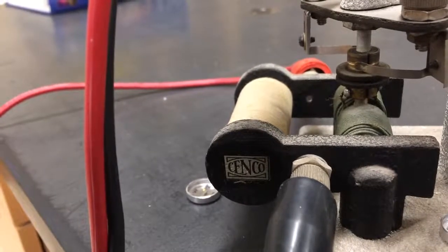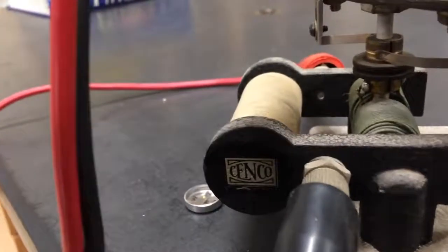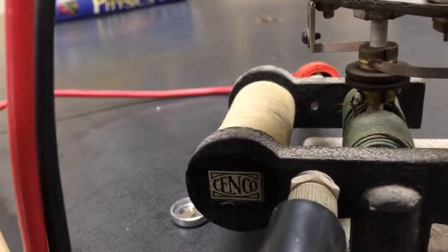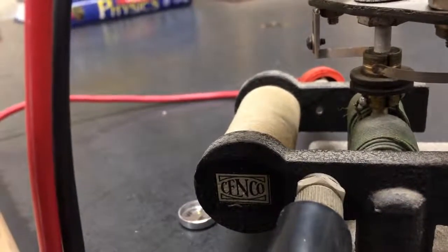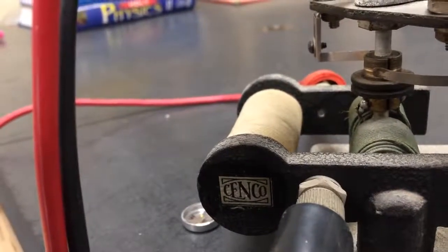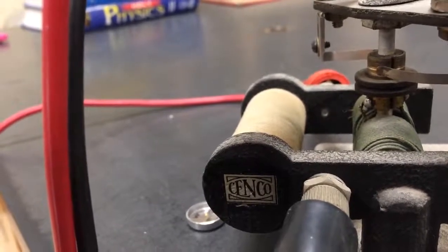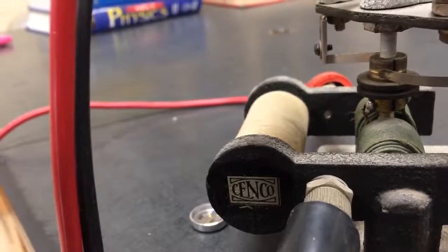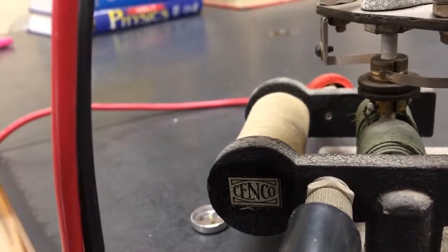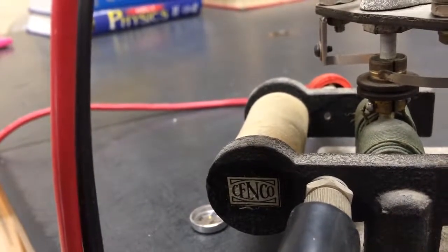And they alternately touch one side of this metal spinning jacket or the other. And what that means is it's constantly switching back and forth, whether positive or negative is touching each side of the jacket, and that means the coil is reversing the direction of its current, just as if it was alternating current.